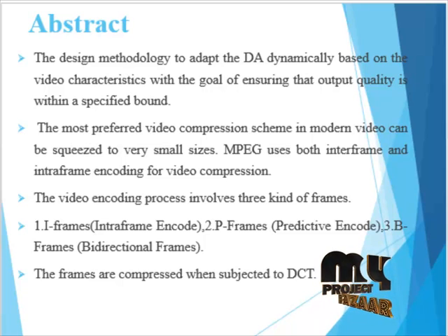Compared with the preliminary versions of our work, this one includes a number of additional features described here. We augmented the design with dynamic and reconfigurable most-significant-bit truncations, which improve the energy-quality trade-off during the video encoding process. We also extend the RAB to include three additional adder architectures: CLA, CBA and CSA. In addition, for the carry-lookahead based RAB, there is a dual mode of carry lookahead with propagate and generate blocks as the basic building blocks.